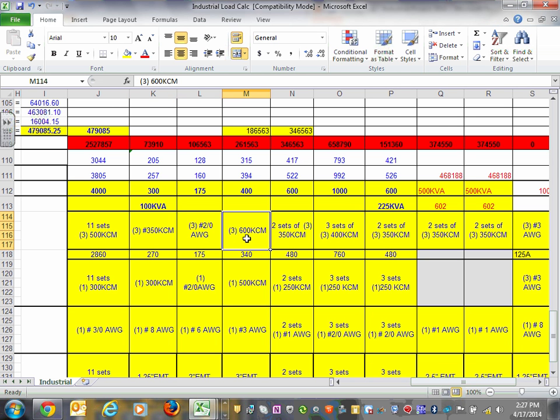And I do hope I did these right. You can check one of them. Here's a 400 amp, for example. For a 400 amp panel, guys, you have 2 options. Either you can run a 500 kcmil and you still meet the code, or you can run a 600 kcmil, and I strongly suggest you run 600 kcmil.